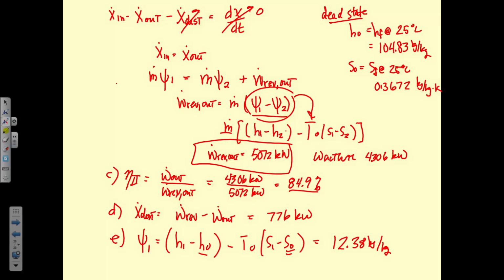No, because if you're assuming that this turbine is operating on water, and it goes down to the temperature and the pressure of the ambient conditions, it's going to be liquid water, right? So it's room temperature water at room pressure, ambient pressure. So if it's liquid water, we'd use the compressed liquid approximation, which is where we go to the saturated liquid-vapor mixture table and just use the sub F values. Even though our pressure is higher than the saturation pressure on those values, it will be approximately the same liquid properties, because water is incompressible and all that.